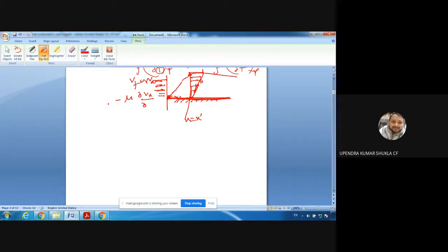Now, since all the layers are not moving with the same velocity in this zone, you will find the velocity gradient in this boundary layer. Above it, you will not find any velocity gradient, because you will find the uniform velocity. So no velocity difference, hence no velocity gradient. This is the direction y, let's say, and this is the direction x, and we are taking Vx as the x direction velocity.